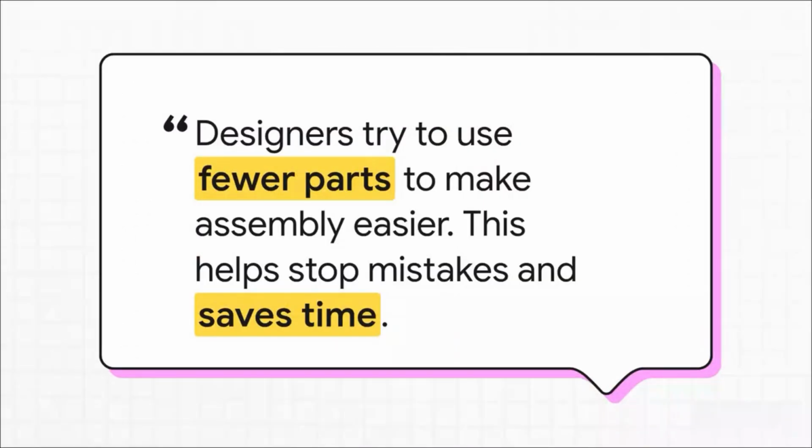And here's a really key piece of wisdom from the design world. Smart fabrication isn't just about making cool, complex parts. It's about making the assembly as simple and foolproof as possible. By designing products with fewer individual components, you automatically reduce the chances for error, you speed up the whole process, and at the end of the day, you save a lot of money.